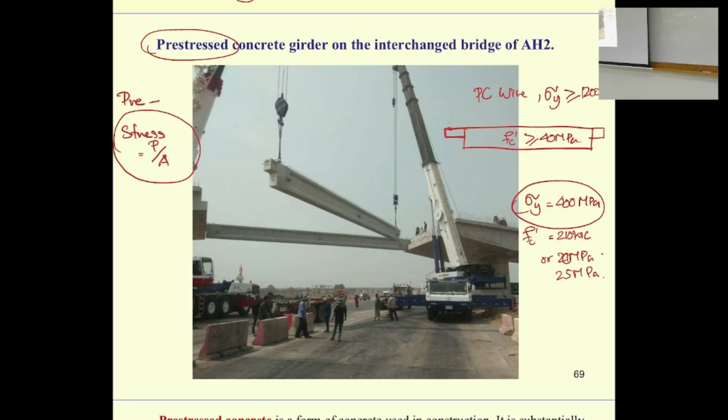Do you know what happened after the concrete hardened? I just cut it here and then cut it. So, do you think what happened next is the wire over here trying to go back to the same shape? Which means this wire is going to be the stress to the concrete like that.